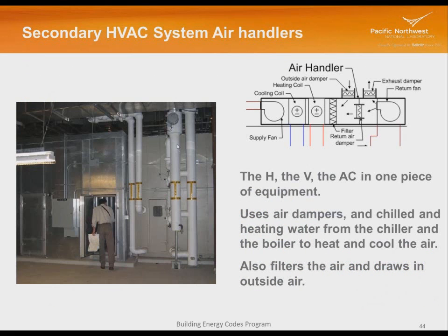Another air handler example, this one rather than up on the roof, is in a penthouse or located in the basement or up in the attic of the building indoors. You can see we've got those chilled water and heating water pipes coming in. There's some coils hidden inside there. We've got a door we can walk in here to inspect the filtration systems, look at the fan. We've got actually multiple doors. We've got a control cabinet, probably a variable speed drive in here for the fan.